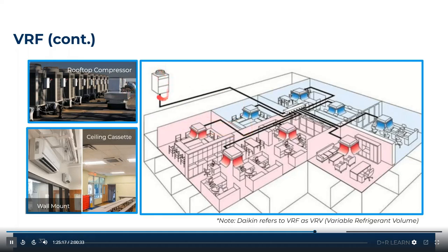So to the right here, we can see we have our one outdoor unit and 1, 2, 3, 4, 5, 6, 7, 8. So up to 8 systems we've got here. I believe the VR systems can work many more, but it depends on the capacity of that specific system by that specific manufacturer. But what you can see here is you have a branch unit that is able to branch off the refrigerant and the flows of that refrigerant to the systems that it requires in each zone.